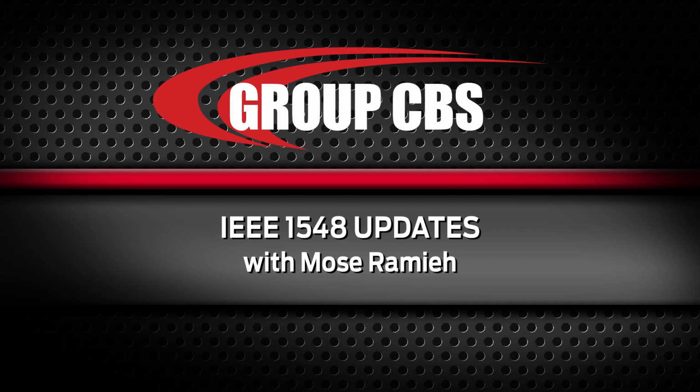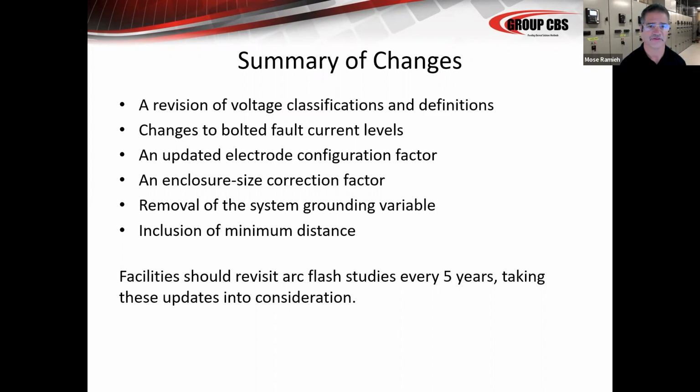Just a brief summary of those changes. There's been a recent revision to the voltage classifications and definitions, aligning low voltage, medium voltage, high voltage with other standards. There's changes to voltage fault current levels, an updated electrode configuration. And what that basically means is if it's horizontal bus or vertical bus, that has different arc flash values based on those orientations. And so the new software incorporates that type of data into the calculation.